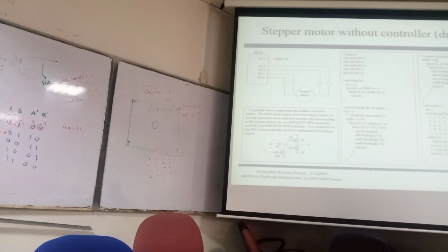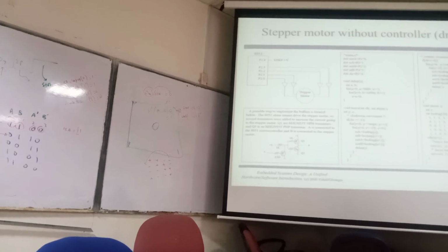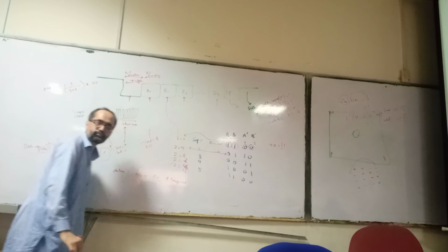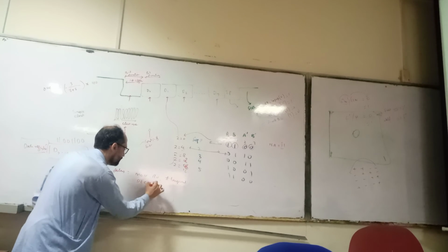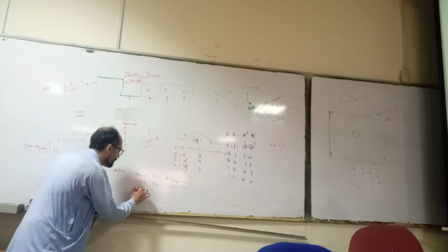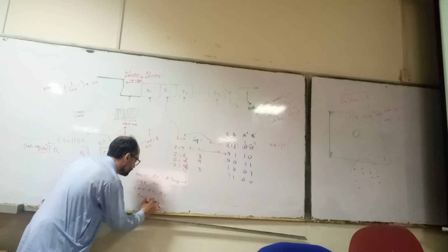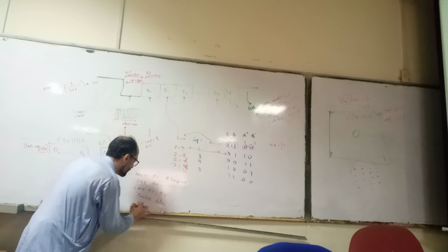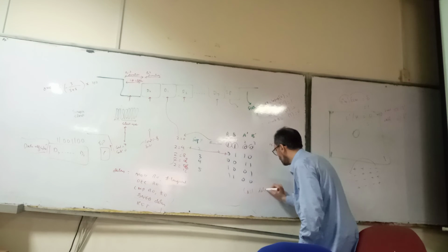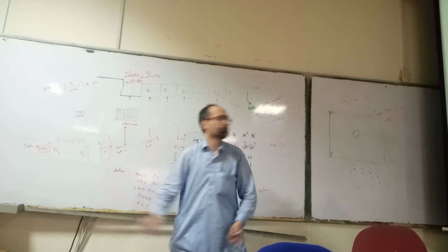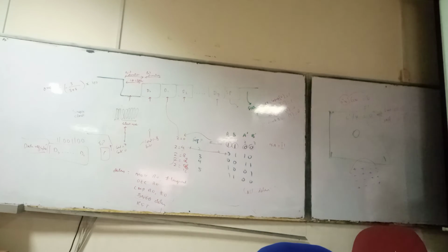So you can see what the delay routine is. Delay can be like this. Move R0 with some large value, decrement R0, compare R0 with 0, branch not equal, delay, and RET. And if you want to call this delay, we can say call delay.